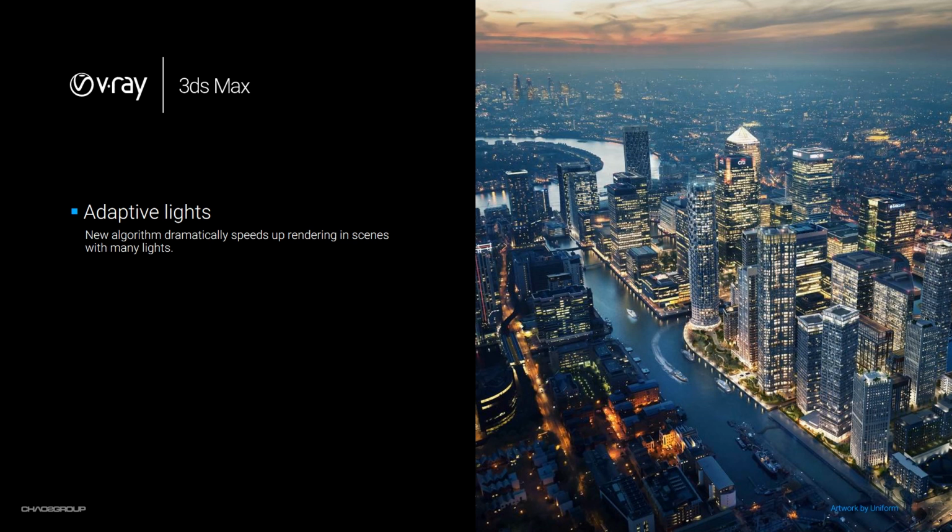Scenes with many lights were quite a challenge to render till now. In VRay 3.5, you have the adaptive lights method, where VRay will pick very smartly only the most important lights in the scene for evaluating the lighting. The more lights you have in the scene, the greater will be the difference in the render speed. Tests show that with adaptive lights on, you can render up to 7 times faster depending on the scene. It is available for CPU and for GPU.